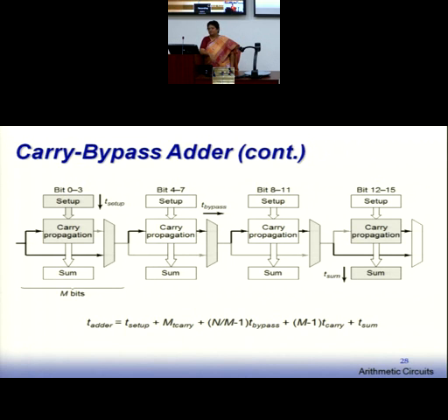Can I stop here? Can I not include the other 2 terms because my final C16 has come to me? Can I say C15 has come to me? The carry at the 15th bit position has come to me. Carry at the 3rd bit position, carry at the 7th bit position, carry at the 11th bit position and carry at the 15th.